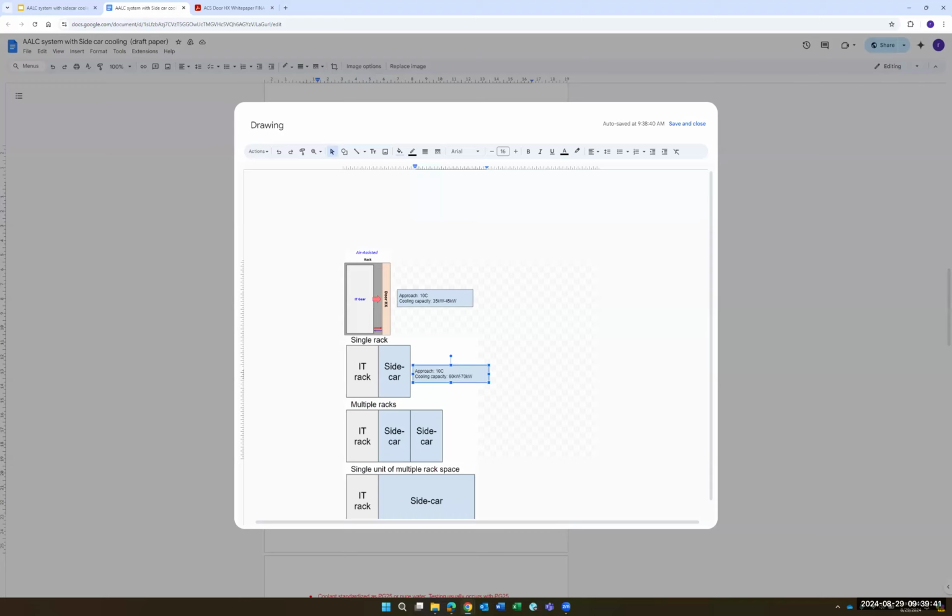But yeah, I think the point of the presentation is that the rear door heat exchanger has an upper bound of 45 kilowatts, and if I start filling this thing full of NVIDIA GPUs, if I had an existing system that's rear door, and I start upgrading my servers that are in there, and I'm using newer GPUs, and my thermal capacity now is exceeding 50 kilowatts, I need another cooling technology, and a rear door heat exchanger has met its limits.